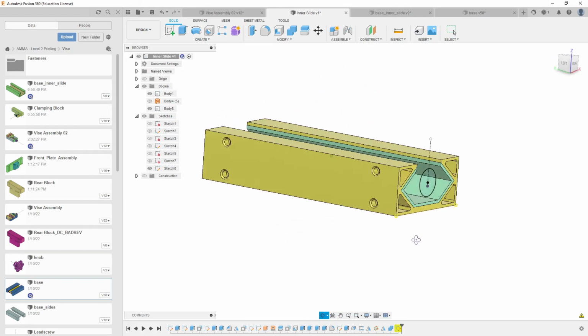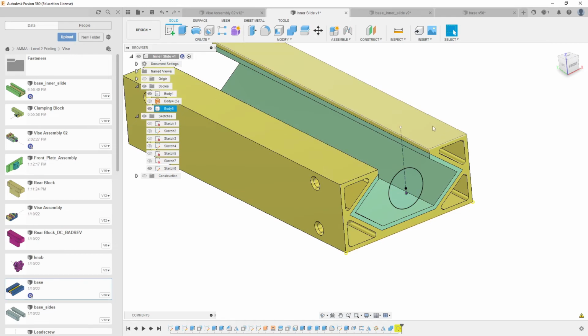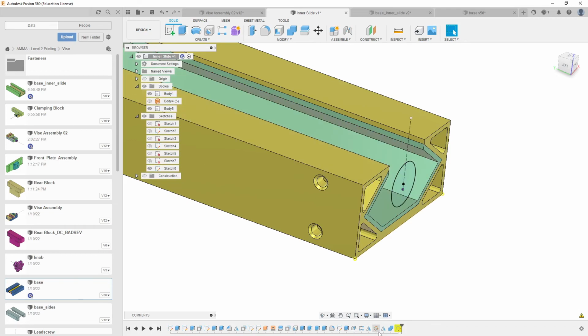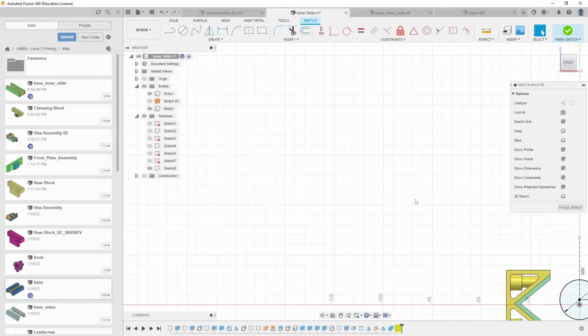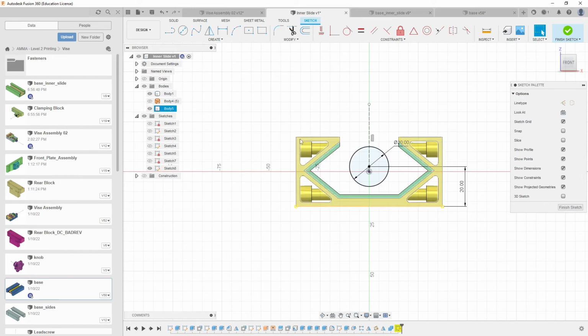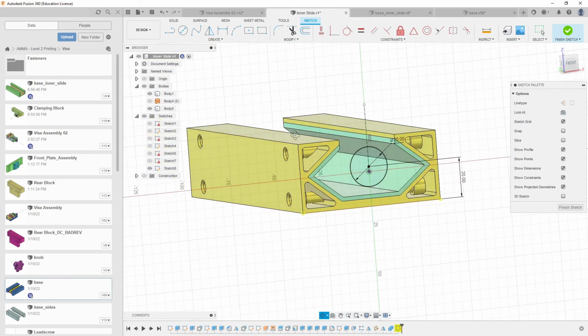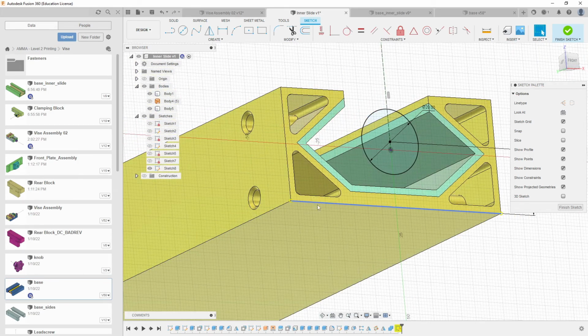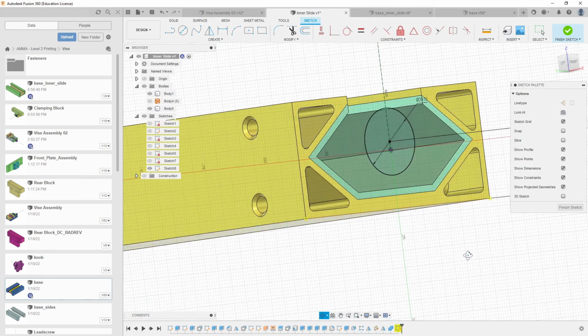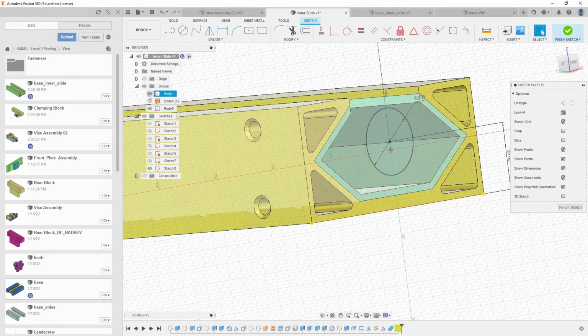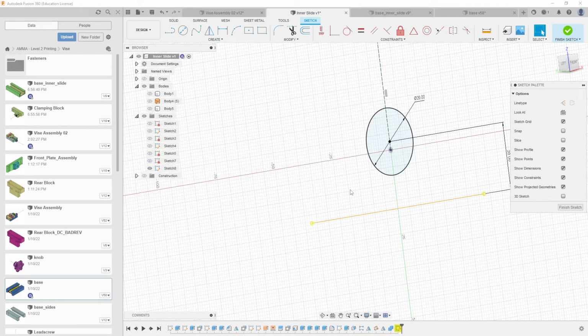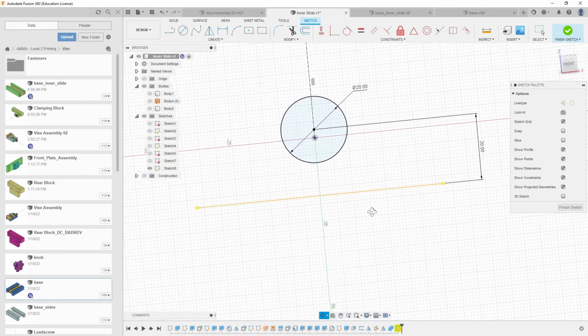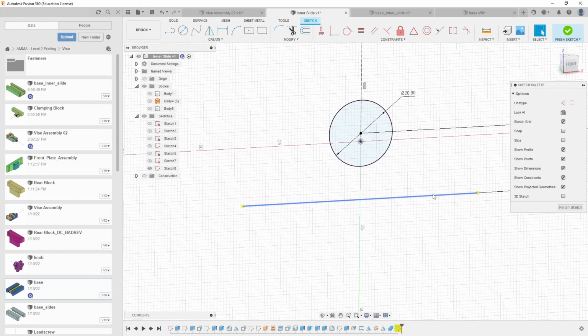So what's going on now? Well, I changed the dimension. I changed the height. There's this height up here, and somehow or another, it caused a problem with this sketch. So I can go here and I can double click on it and I could edit it. I could also right click and review the warning, and oh, it's a projection. So even though we didn't change the face down there, see this yellow right there? It's always really hard to see. I could turn off the bodies here, and maybe you can see it better. This is their error warning. It's saying that there's something wrong with this. So I could redefine the projections.